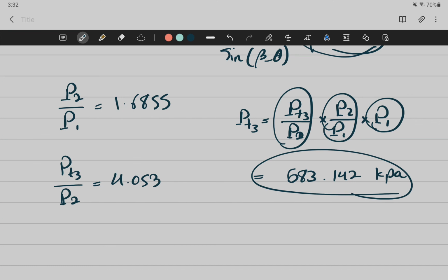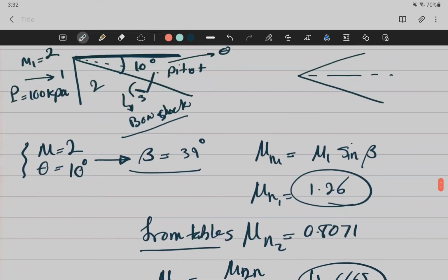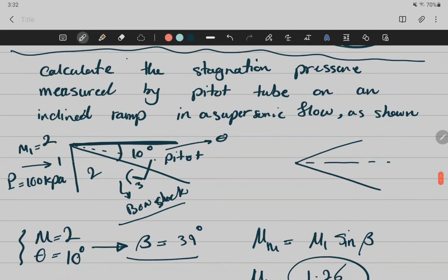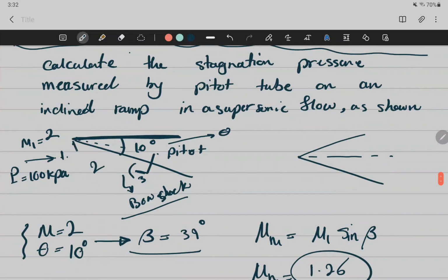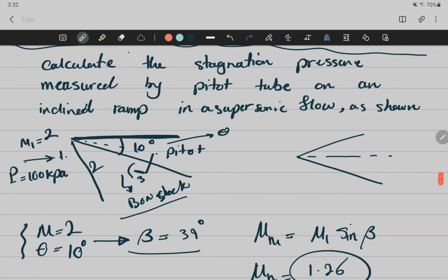So, what direction is that Mach 2 flow in? I'm getting confused with what's the normal direction, what's the X, Y. Okay, this normal direction is going to have two components. Let's say this is, it should be 39 degrees, so the shock is like this, right? We are going to have one normal component like this and one tangential component. This is going to be M1N. Then we're going to have M2N.